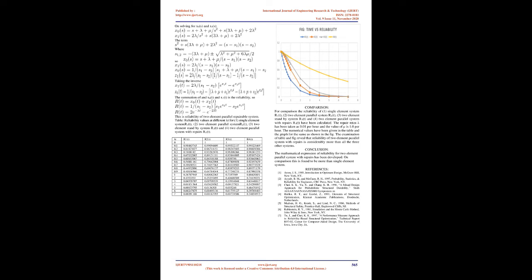B. MTTF, mean time to failure. It is the expected time to failure of a redundant non-maintained system. Example: a vehicle in outer space having redundant viewing systems inside. C. MTTFF, mean time to first failure. It is the expected time that the redundant system would take to reach the total failed state, while maintenance on failed items is started immediately on their failure. Example: many thermal power units in a power station.